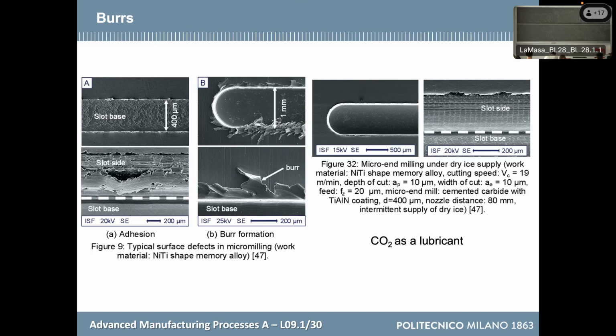The ultimate tensile strength increases, and in terms of chip, you can even create a fluid chip. The correct name in the field is ductile chip, even if you are machining a fragile material. So this is the good side of putting pressure on the material. This is also used in macro cutting. For example, if you have to turn a hardened bar of material, I don't know, at 55, even 60